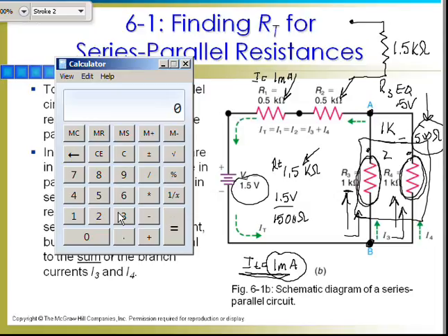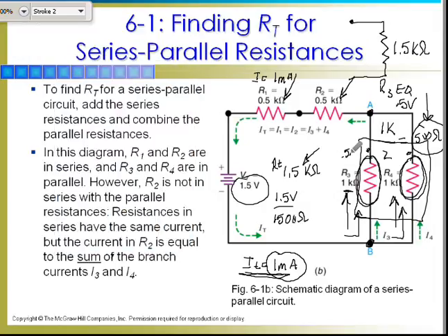this resistor R3 here, 0.5 divided by 1000, is going to equal 0.5 milliamps flowing through this resistor. Since this resistor is the same value, and you can see two equal values, I've got 1 milliamp going in. I'm going to have half a milliamp of current going through each separate branch. But once I get back to point A, that will combine again into 1 milliamp.